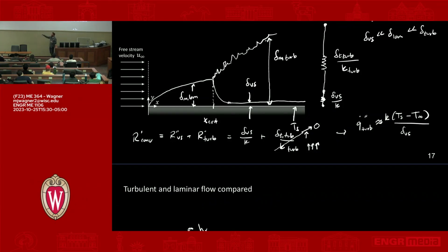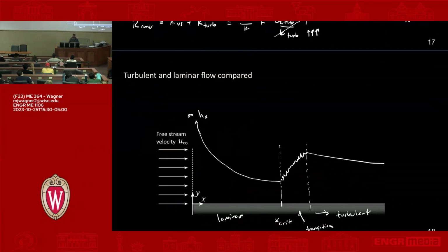So as long as that turbulent boundary layer is growing, the shear forces in that boundary layer are dropping as it grows. The viscous sublayer is going to continue to react to that layer growing and slightly grow and slightly grow. Until at some point, maybe that boundary layer interacts with something else and you start getting constrained boundary layers. But at least in external flow, the viscous sublayer will continue to grow indefinitely. So as we draw it down here, this heat transfer coefficient needs to continue to slightly drop as you go. Other things to point out.